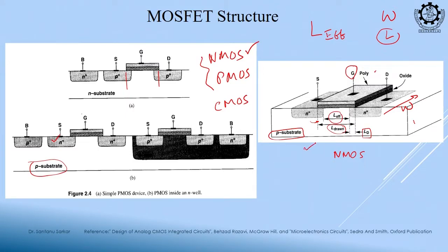So, you could make only NMOS devices. Then after some time PMOS only technology was also developed, and nowadays both N and P can be fabricated on the same wafer, same substrate. So, this is termed as complementary metal oxide semiconductor. Complementary means N and P are complementary. So, we use both of them. So, it is CMOS. NMOS we already know: on top of P we are building